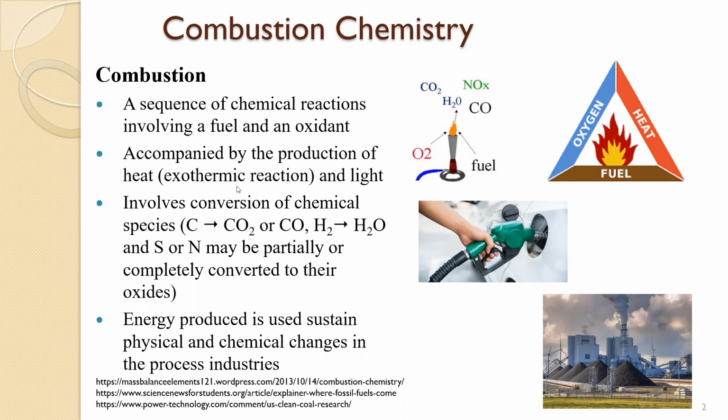It's accompanied by the production of heat, as I said, and it's exothermic in nature. It involves conversion of a chemical species. So the carbon would either convert to carbon dioxide for complete combustion or carbon monoxide for incomplete combustion. H2 converts to water vapor, and then sulfur and nitrogen in the fuel may be partially or completely converted to their oxides. So SO2 or SO3, NO2 or NO3, depends on what is being stated.